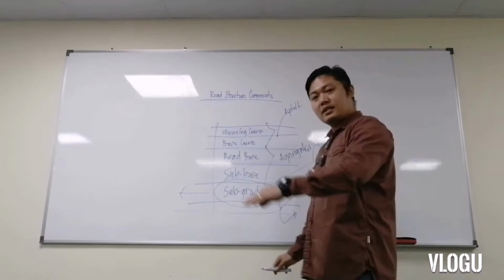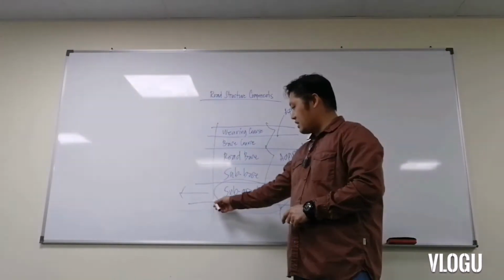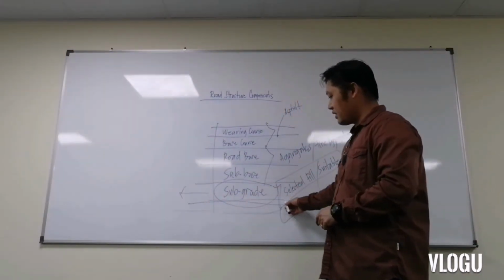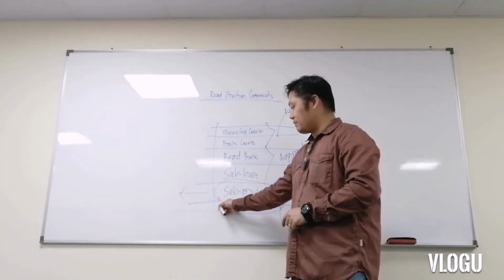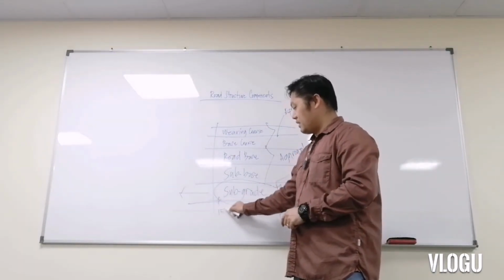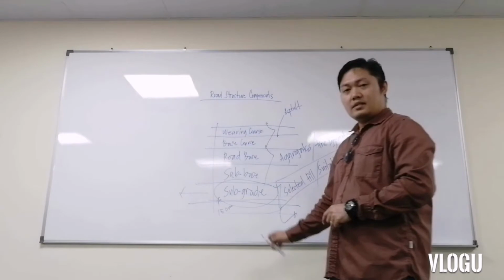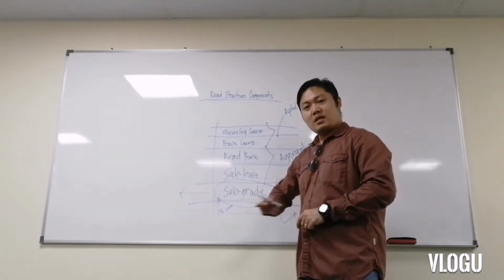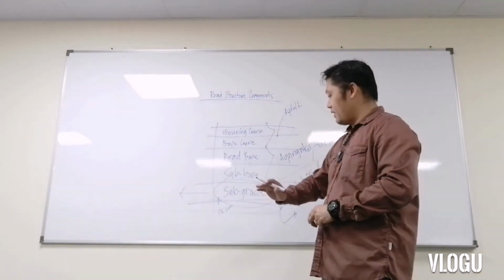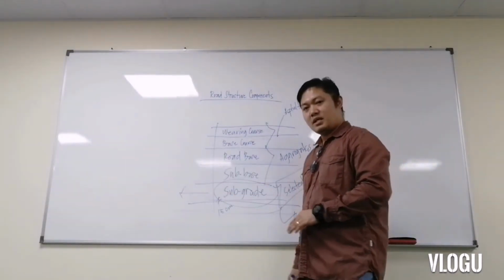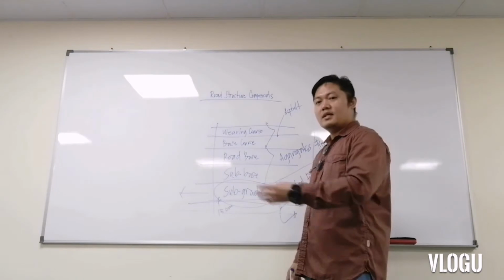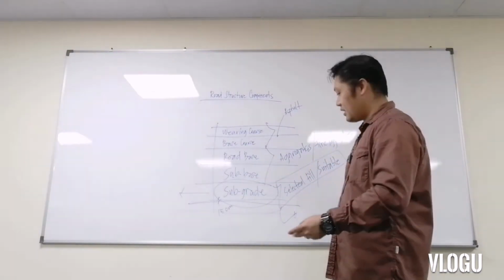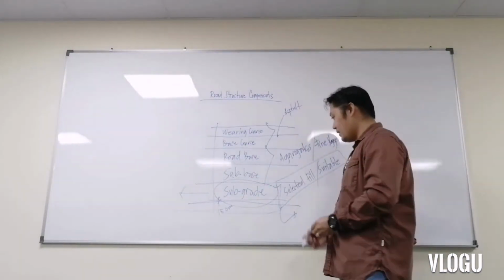Selected fill, these are the new materials to be used in order to backfill this area, which we're going to backfill in layers. So each and every layer, based on specification requirements, we are going to compact at 15 centimeters in thickness, and at the same time we are going to test that based on field density testing by means of nuclear gauge or sand replacement method, also known as the sand cone method.